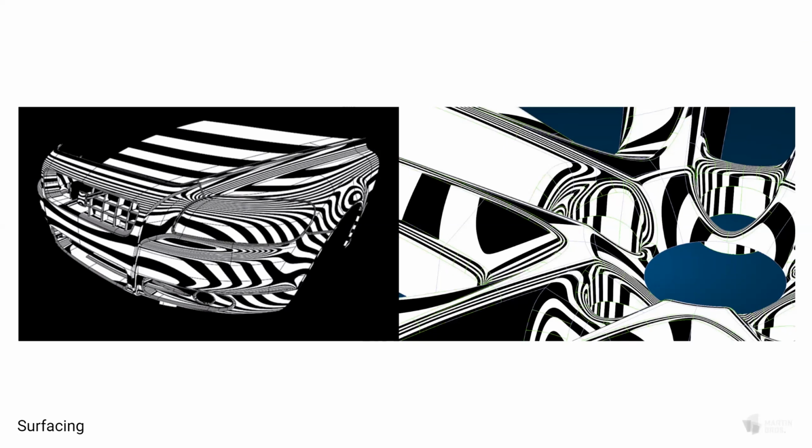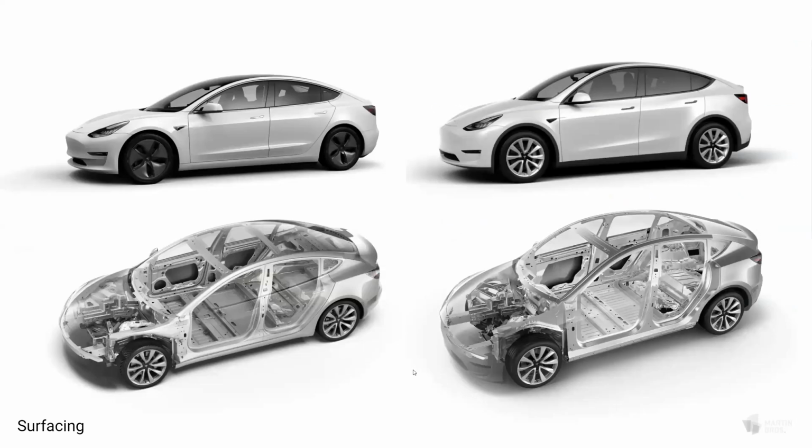You get more bang for your design buck. Obviously, a car is symmetrical. The spokes on the rims are arrayed radially, but even if you can't find exact duplicates in the A surface, you can still find opportunities for repetition in the substructure. In an automotive facelift, you keep certain major components and apertures the same, but you're free to change everything else in between, creating the appearance of variability while being able to reuse much of the design and engineering of the B side.